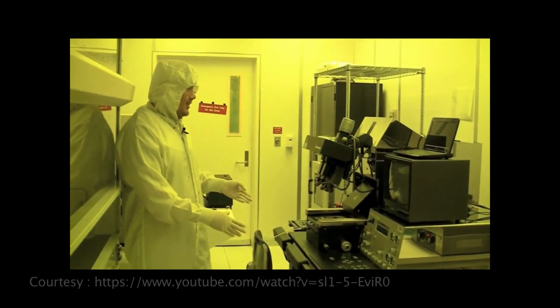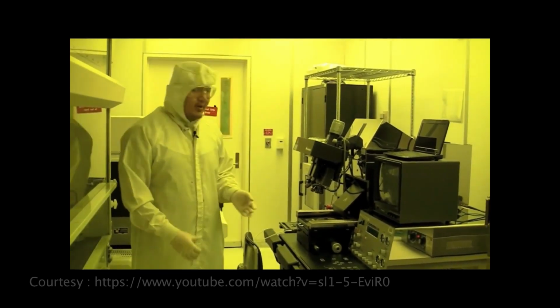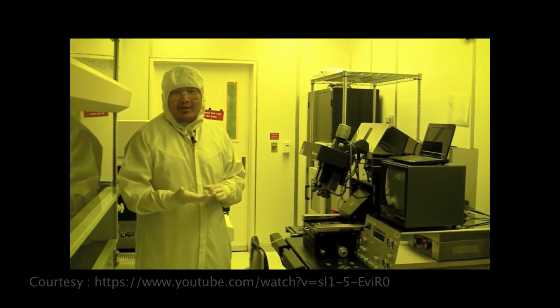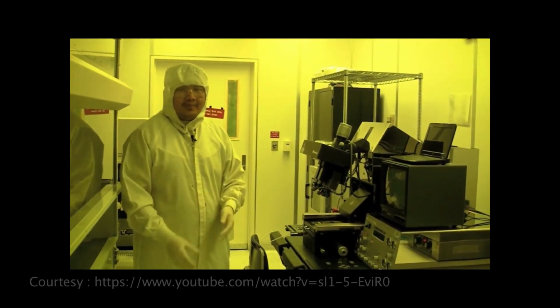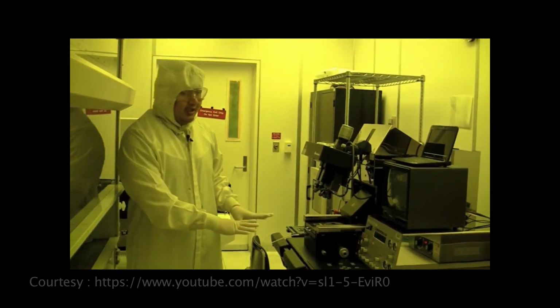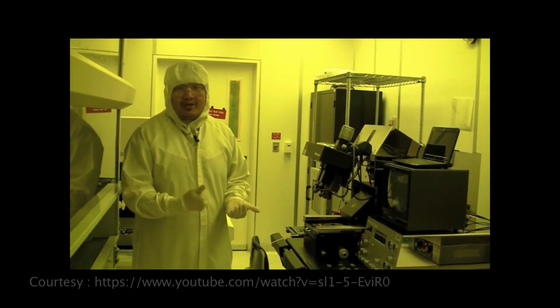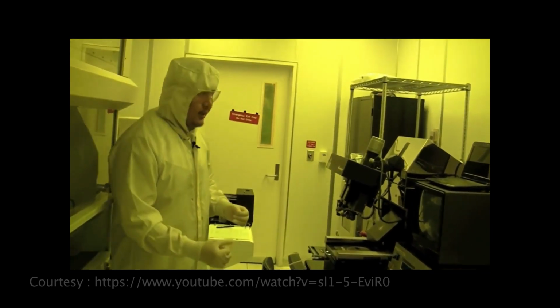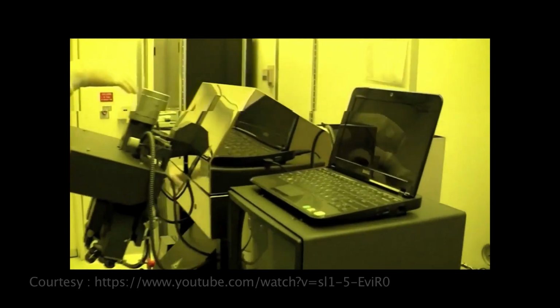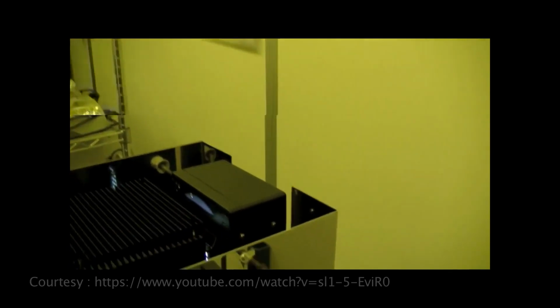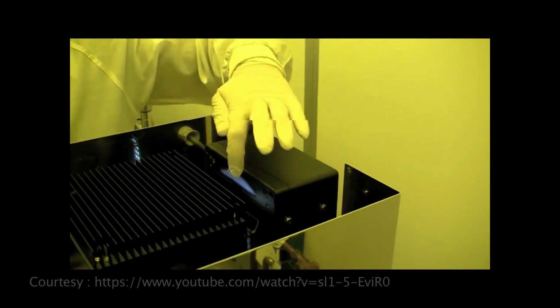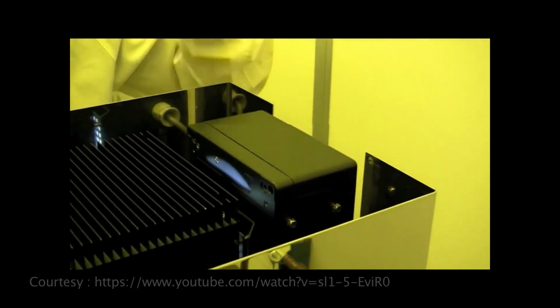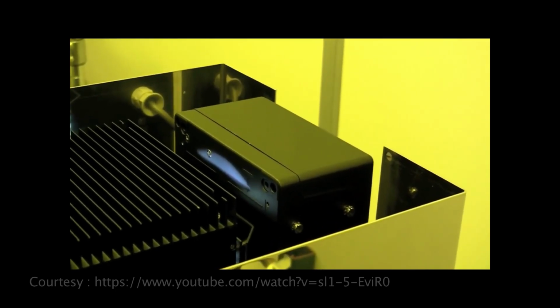This is the MA6. It's used to expose UV light to your substrate that has photoresist on it. So before we run the machine, the first thing we have to do is make sure the light bulb is turned on and not blown. So we come out to the back, and you can see the light is turned on by the reflection here, or you can see the light glowing. So you know that the light bulb is on.